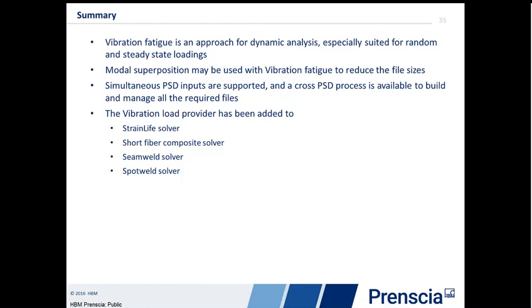We also see that when we're doing a modal harmonic analysis, we can actually leverage mode superposition, save only the stresses from the mode shapes and then the modal coordinates from the harmonic analysis, and with that we can significantly reduce the file sizes and hence speed up the analysis.